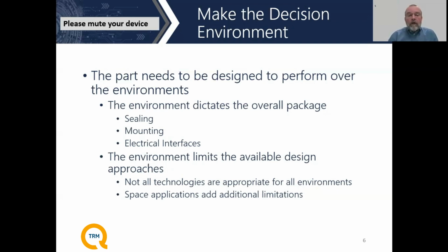Does it need to be sealed? Does it need to tolerate salt? What sort of mechanical mounting considerations are required for the system? And how are we going to connect this electrically? Will it be an SMD type device? Will it have connectors on it? Is it a very high power device, in which case does it need very large connectors? Does it have a high altitude sort of environment, in which case you have to start worrying about critical pressure, or in space applications where you have to worry about multipaction effects, due to those sorts of breakdown considerations in very low pressure environments.